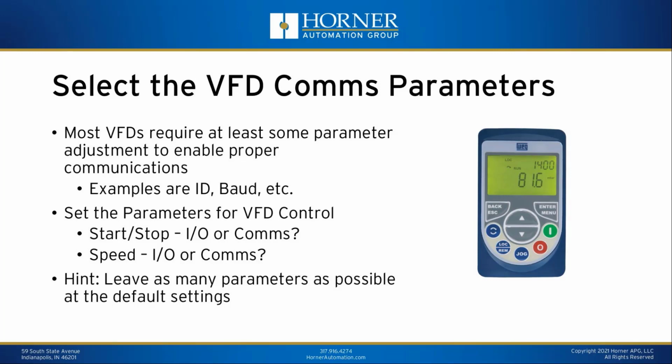And again, a hint I would give, just as an old applications engineer, is leave as many parameters as possible at the default settings. It'll make it easier not only on yourself when it comes to setting up the system the first time, but if you ever need to swap out a drive or the electrician ever needs to swap out the drive later, he'll thank you because there'll be fewer parameters to change on the drive side. That being said, when there are parameters that you want to change to get the machine to operate better, that's another scenario. But if you're not sure if you should change it or not, and it really doesn't affect the operation of the machine, my hint to you is leave as many defaults as you can.